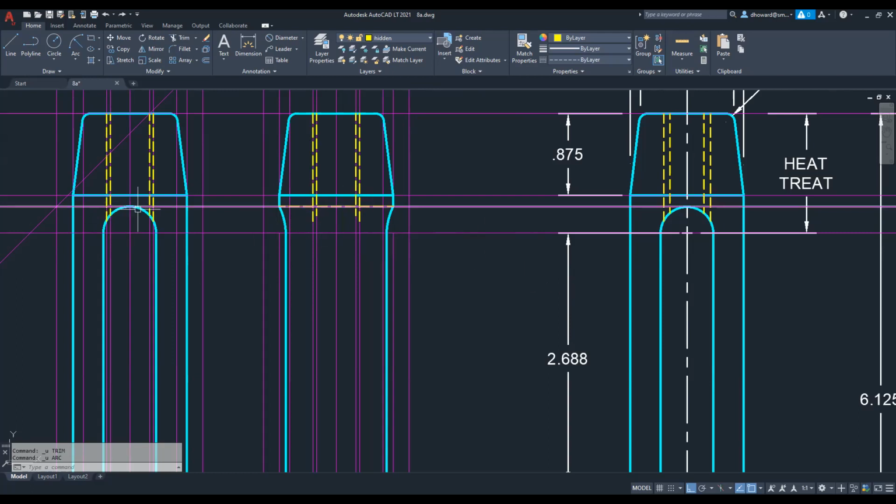So this is the top of the hole, this is the top of the slot that the hole pierces through. And so what is customary to do in drafting is just to show the top of the piercing. And that is it right there.